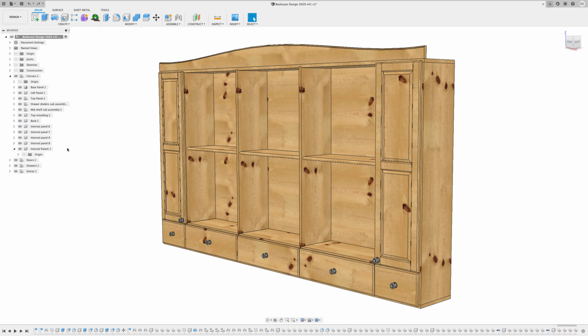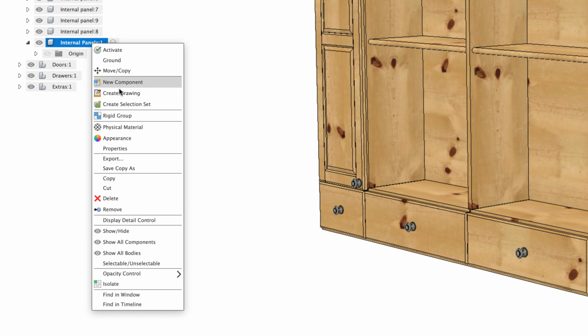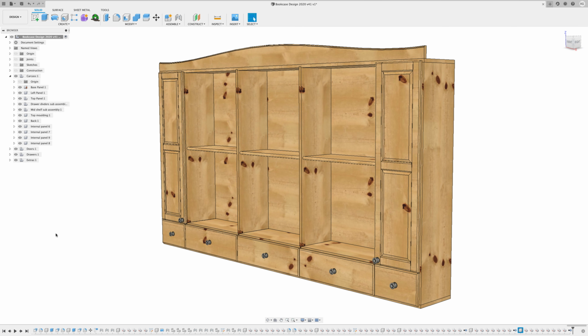What you can do instead is right click on this, and there's a command here called remove. Now if you use the remove command rather than delete, that will take the subassembly out of your tree, bang, but it still retains the reference inside Fusion, so your project will still work. So you could use that to reorientate these as you wish. I'm happy with my subassembly, so Control Z twice to put that back into place.